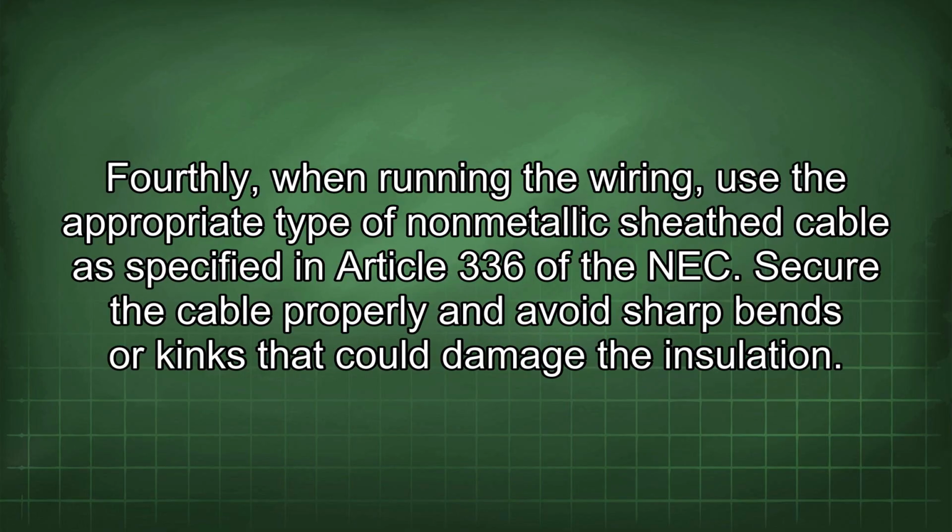Fourthly, when running the wiring, use the appropriate type of non-metallic sheathed cable as specified in Article 336 of the NEC. Secure the cable properly and avoid sharp bends or kinks that could damage the insulation.